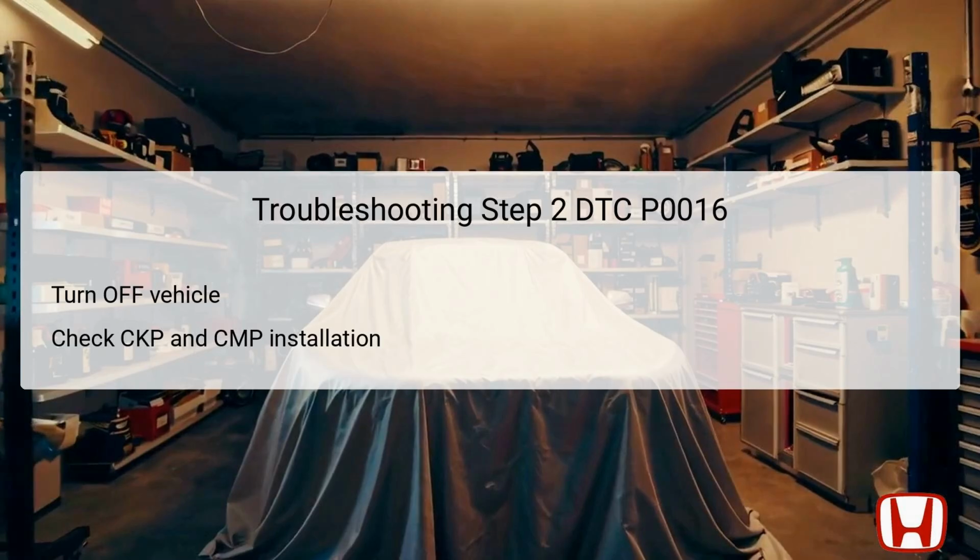In the third troubleshooting step, the technician must remove CMP sensor A to gain access for inspection. After removal, a detailed visual check focuses on the CMP pulse plate A, which is essential for the sensor to function correctly.